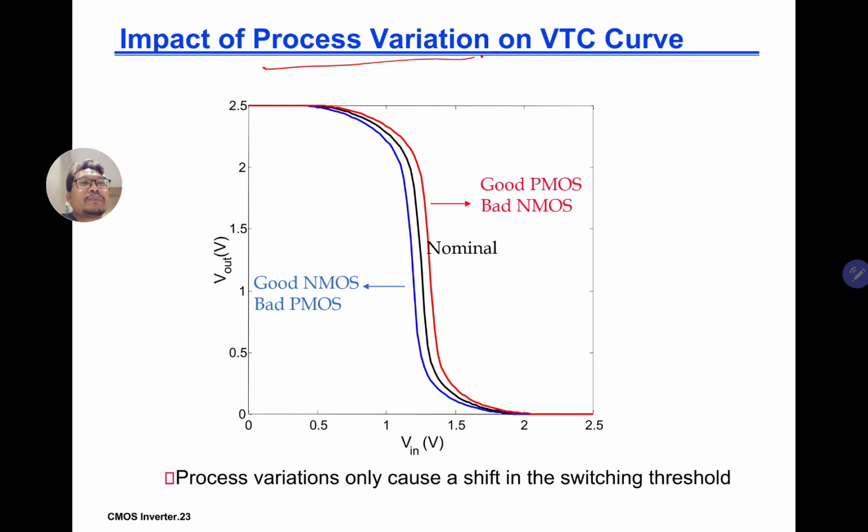Normally it becomes smaller. Of course, in your calculation and drawing, you did it perfectly: you want 5 micron for the PMOS and 2.5 micron for the NMOS, but in the end when you fabricate, it's maybe less. So then your VTC will shift.